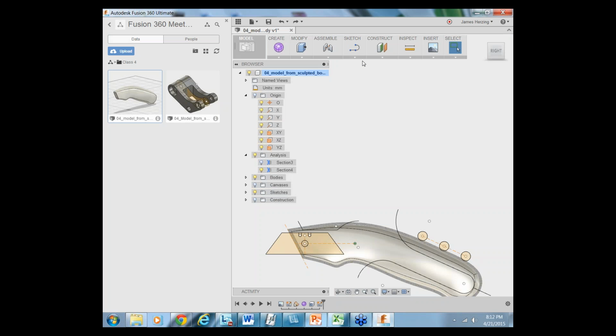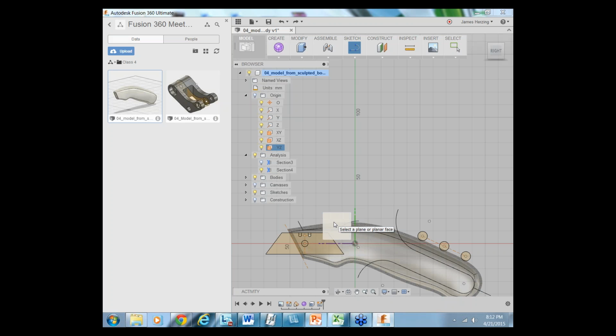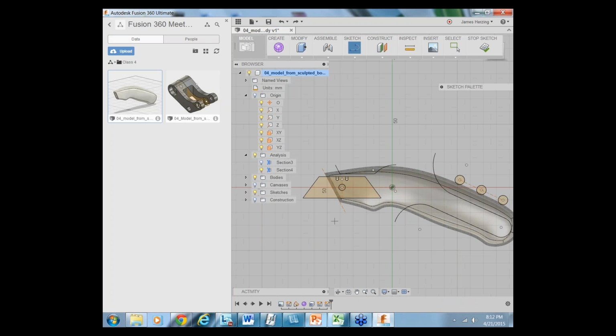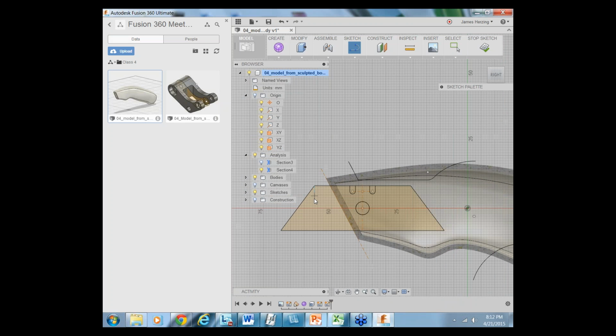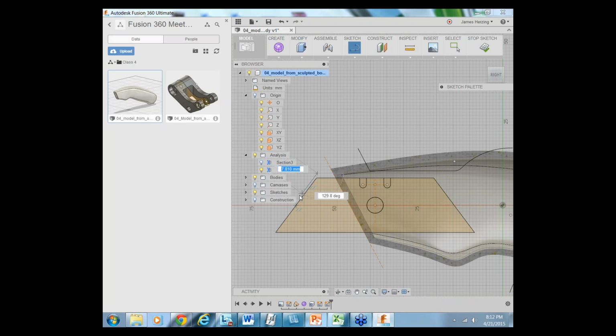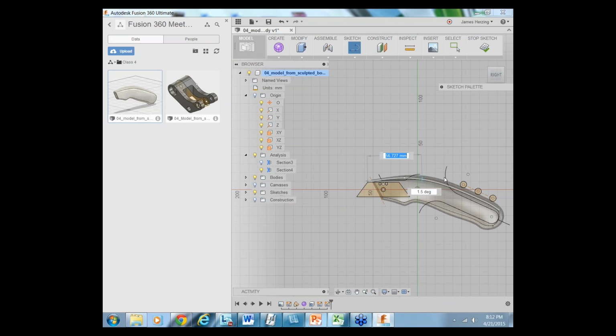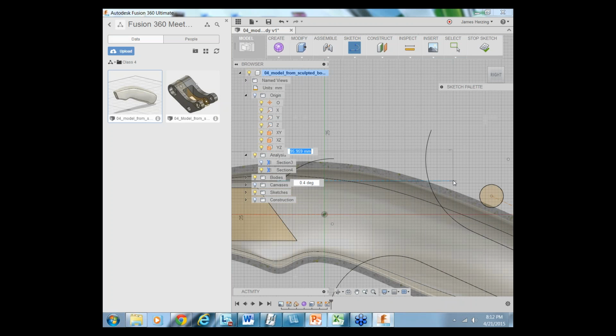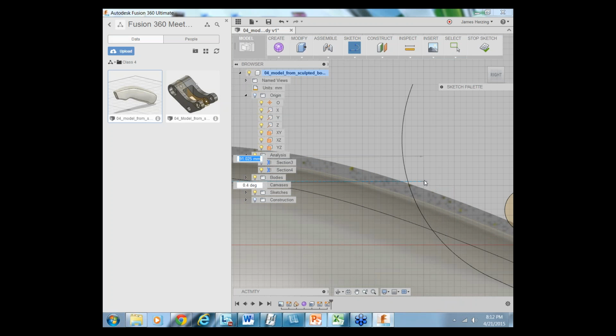So sketching, click on the drop down and choose line. Then there's going to be a plane parallel to us. We click on that and we zoom in, and generally speaking, get to this snap point right above the corner of the blade. So we click and zoom out, and we draw a straight line, let's say, to right there, and click escape.